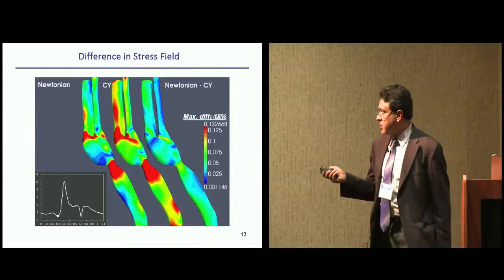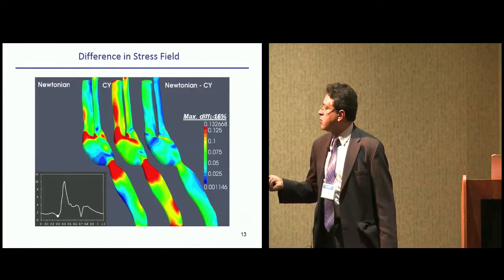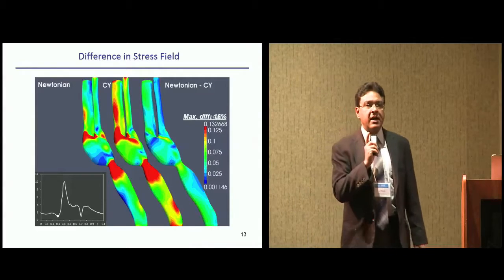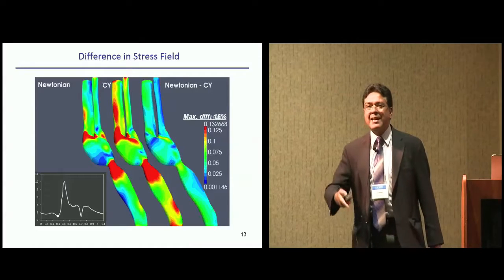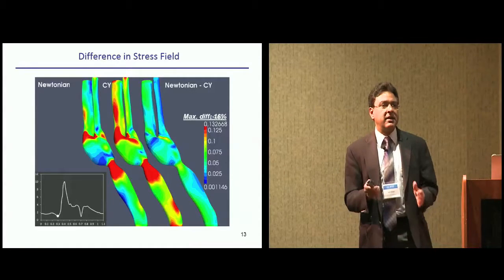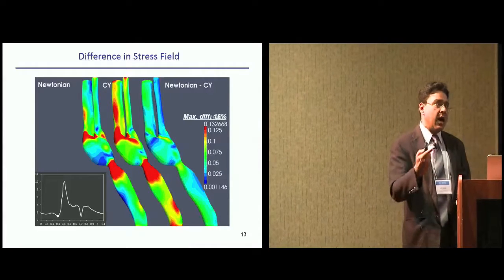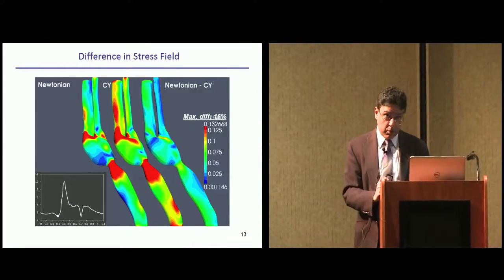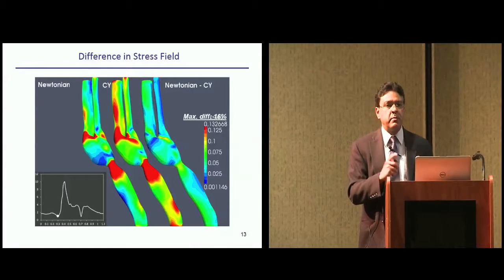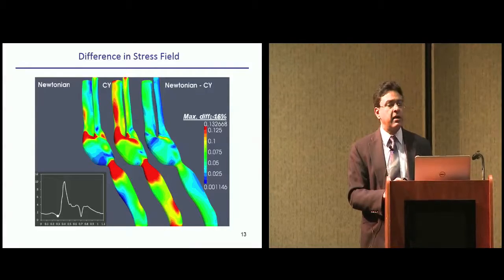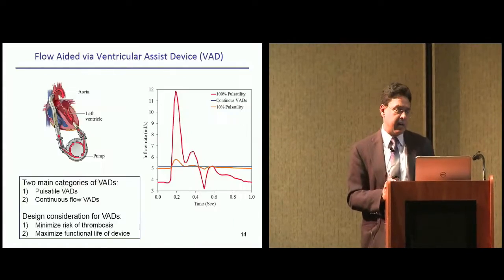So here, the difference is pronounced, but also take a look at that the portion of the peak cycle is 20% of the entire cycle. So 80% of the time, we are predicting stresses which are 16% less than what they are. It is on the non-conservative side. So unless we use numerical methods which are high fidelity, and not only that, high physics models, we cannot use these techniques for diagnostics because we will be under-predicting the stresses. Stresses in the patients are higher, and we are not able to predict it. Risk factor is high. We are on the non-conservative side.